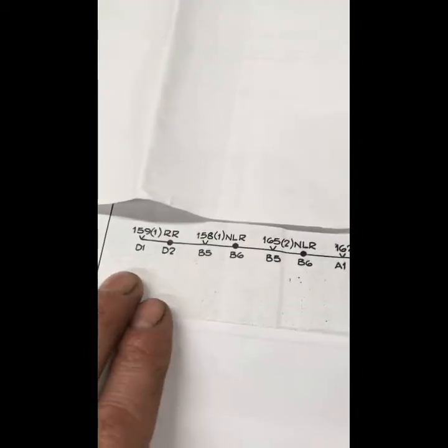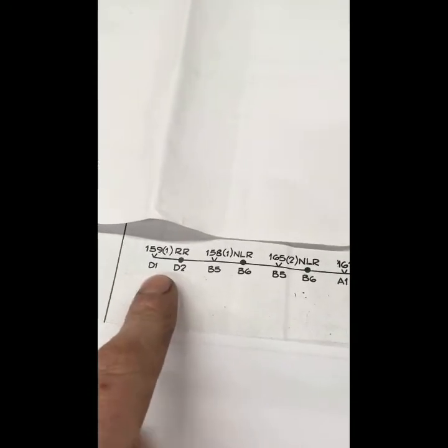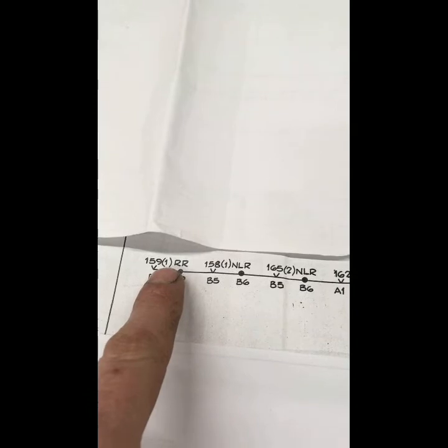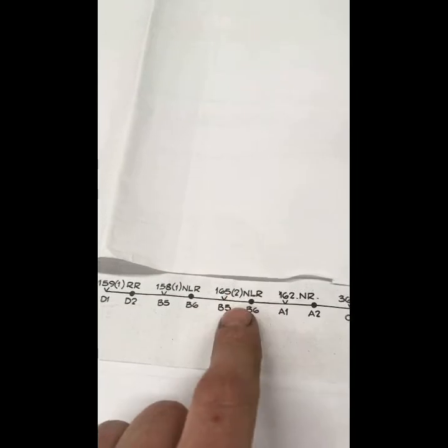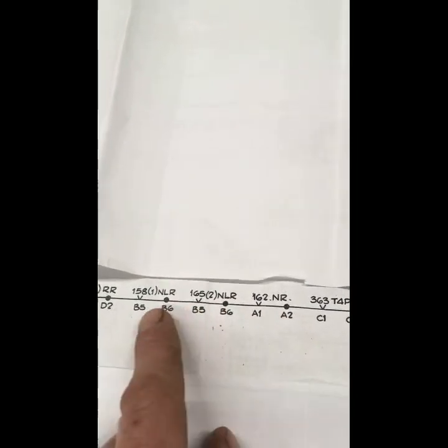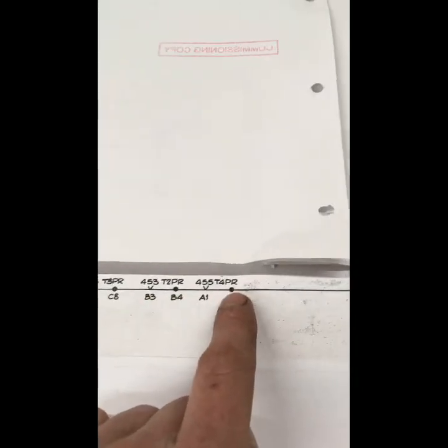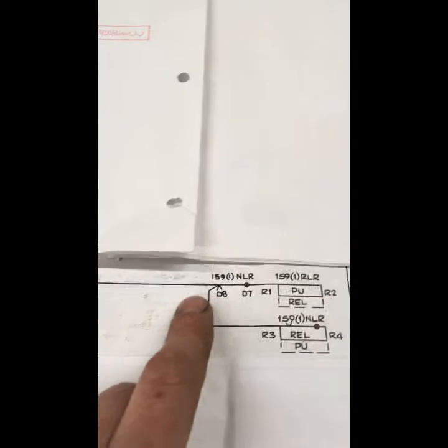You saw on the previous page that we were going to delatch our NLR and clear our RLR to clear our route. So here you can see that now the RR route relay has operated for route 1. That is the opposite route for another signal as part of this. In fact there's 3 of them, these have not been operated, so we don't have conflicting routes. So these are NLRs, our normal locked routes for them are still engaged, so we haven't operated another route, and our other circuits that are required as part of this are all in their correct positions.